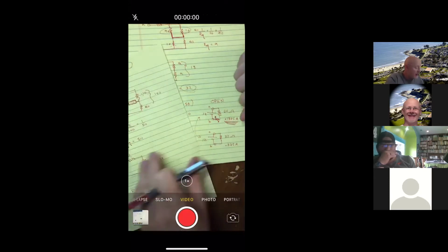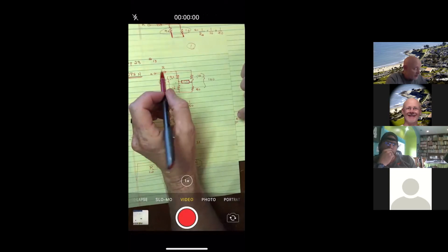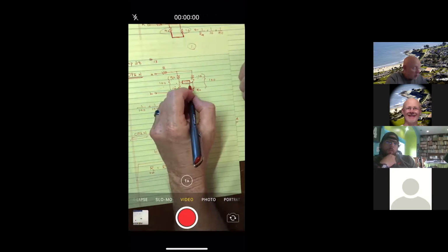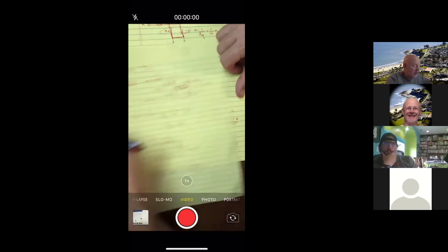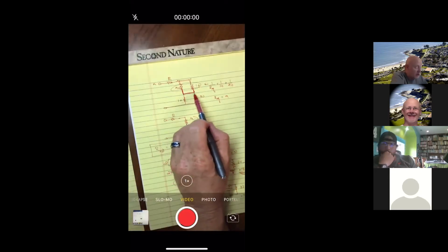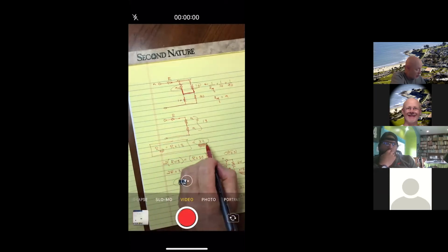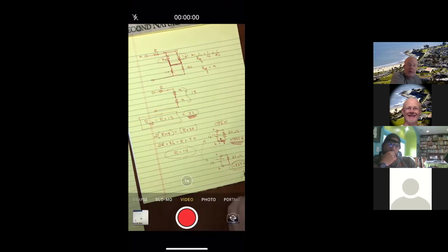But this is the thing that comes to my mind, photoresistors, or phototransistors, because you can set them up so that when the light is hitting them, they're actually a good conductor, and it would be the same as this circuit, which we did with the closed switch, which would result in a resistance of 32, which for the 12-volt battery would result in quite a bit of current, and therefore the light on my dash would be kind of bright.